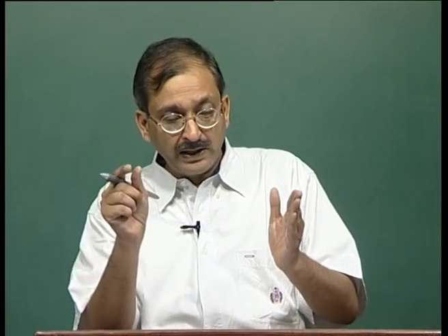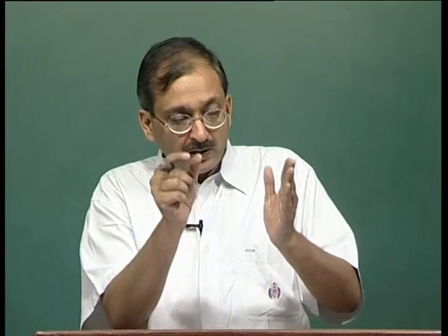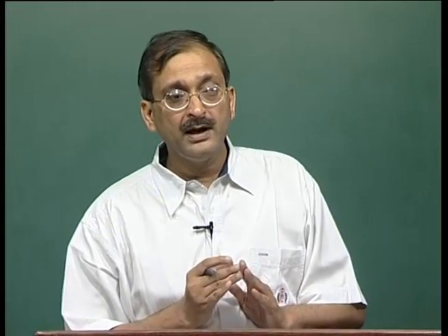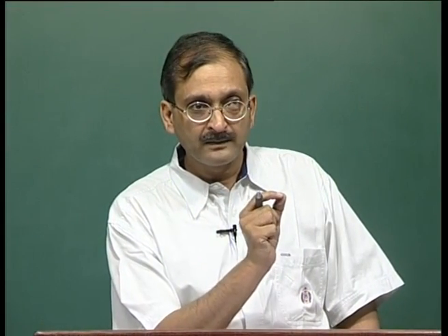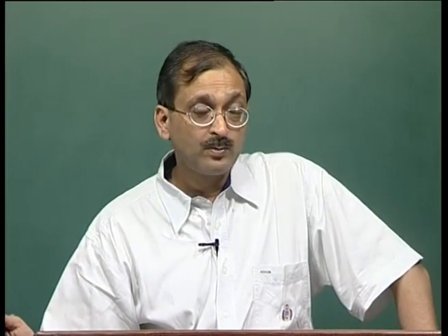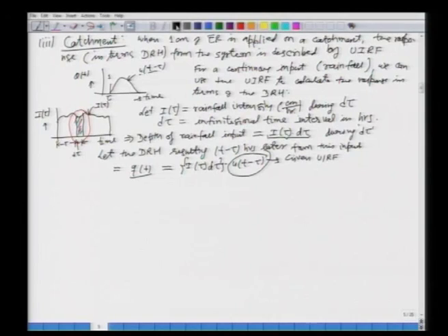All right. How can I now calculate the response from the total rainfall input? Now, this I tau is continuously occurring, and I have calculated the output due to this small strip. So, what I can do actually is, I can divide this whole input into various small strips, and then I can integrate the whole response. All right. So, I will have very small discrete intervals. All right. Again, this is an assumption or simplification. So, I can divide this whole input into small strips of inputs, and then I can integrate, so that I can calculate total response from this continuous input. Okay. All right. So, what does that mean?